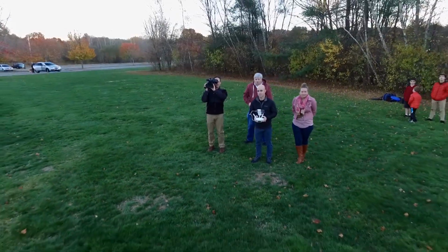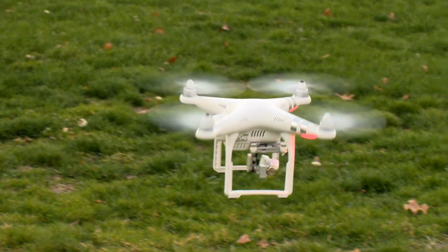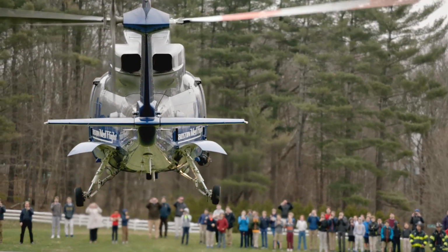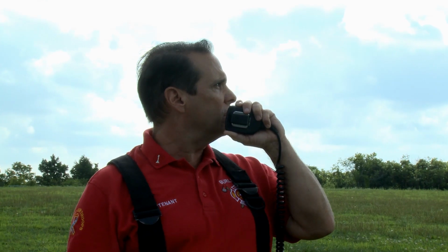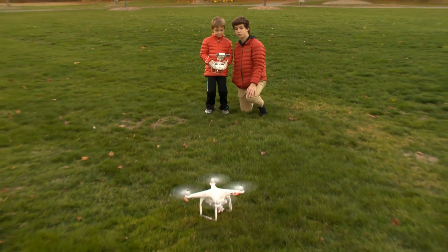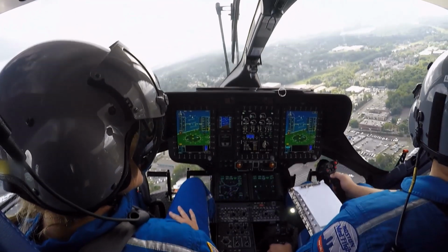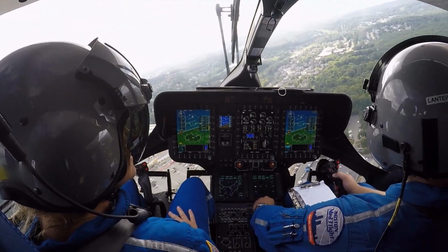Media and onlookers are often interested in getting a better view of the helicopter. Sometimes this will include the use of drones to capture video of the helicopter landing or departing. Drones are an extreme hazard for helicopters. LZ Command must assure any drone near the LZ is securely on the ground before the helicopter begins its approach. Advise the pilot if a drone has been spotted in the area.